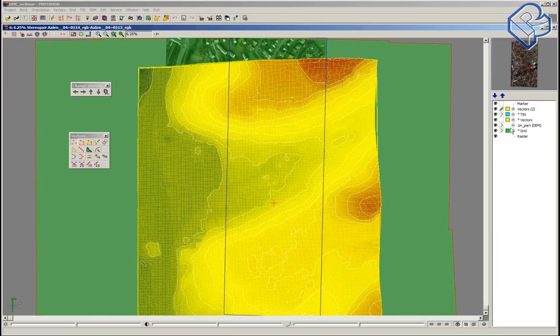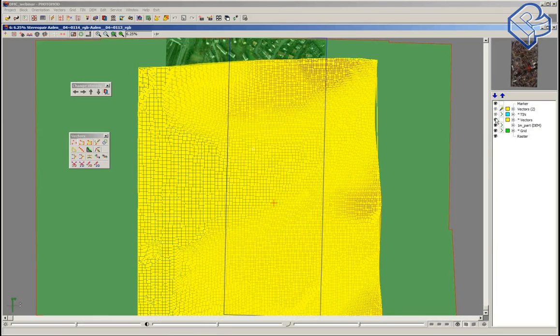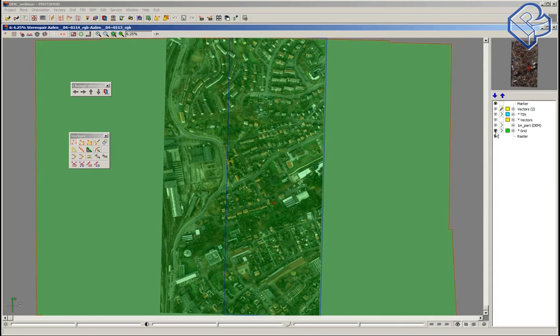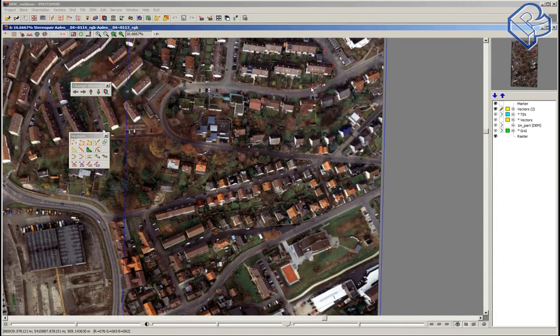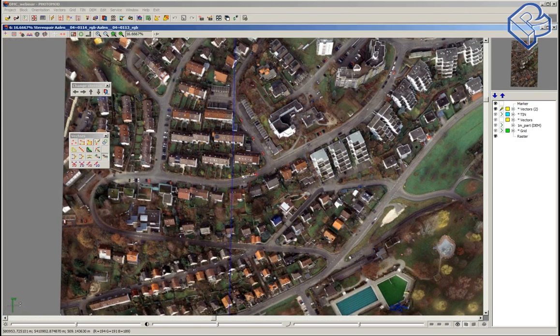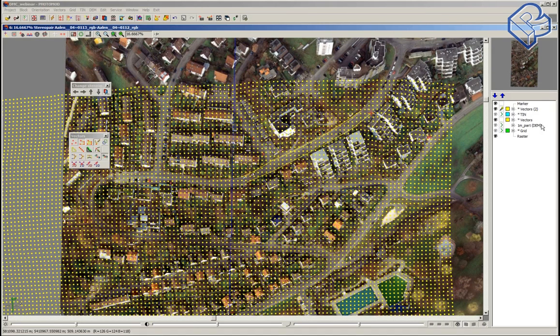Let's look at the stereo pair, for example, without grid, vector here. Just create some lines without stereo mode, if you don't mind. Just line. After I create some break lines in this vector layer, I can use both of these layers for TIN.